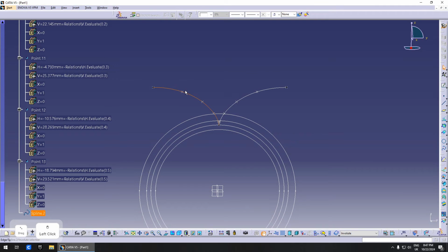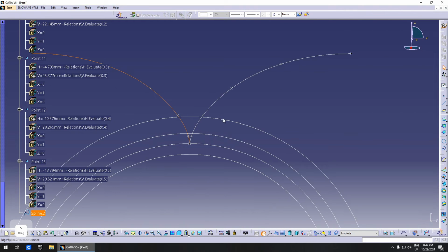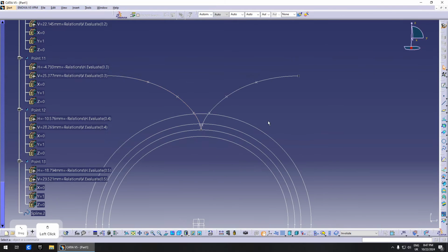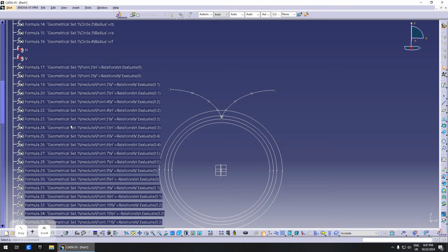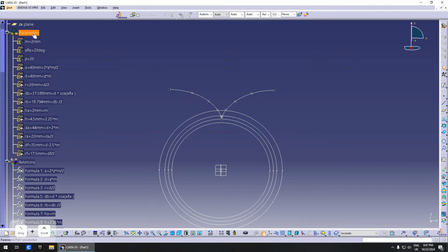Next thing you need to do is to rotate this curve to where it should be positioned here somewhere to create the other flank of the tooth. And in order to do that, there's a different formula. There's a lot of formulas in this video, unfortunately. There's a different formula to calculate the half tooth angle. It's called half tooth space angle. And we need to create it here.